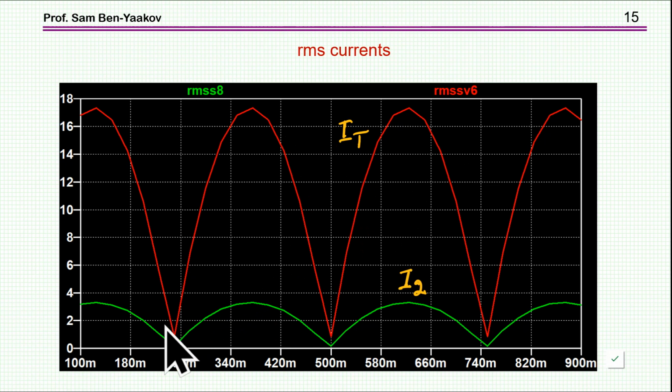So again, I'm going to see here sort of a dip, because the native ripple of the inductor, when summed up of 4 phases, also has a dip. This is like a regular multi-phase interleaved converter, but here we have an additional ripple due to the ripple that is injected from the secondary to the primary. I don't see it. This is not a time domain presentation. This is sort of a summation of the RMS values.